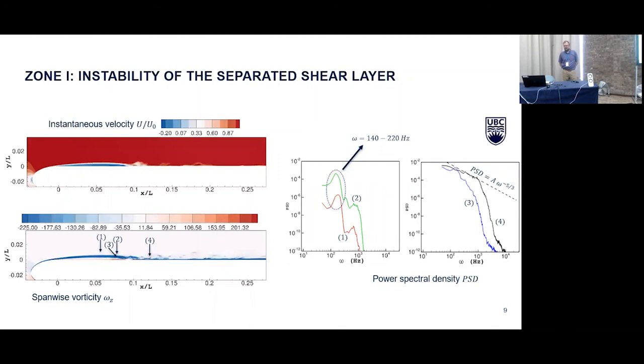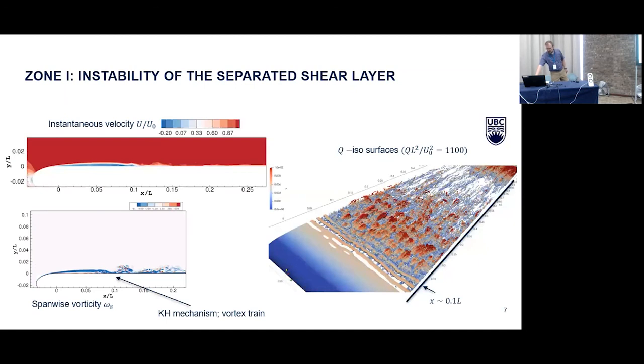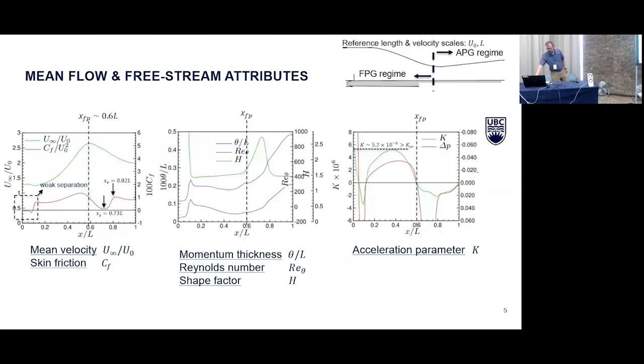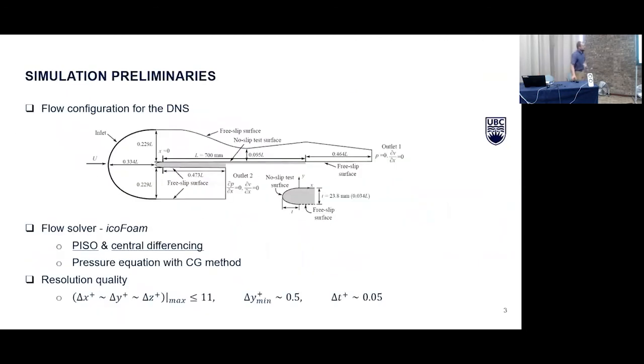One question. Can you comment on your inflow turbulence generation that you use for the simulation? We have no inflow turbulence. So we have quiescent free stream conditions. Of course, there are truncation errors and other numerical noise that result in fluctuations in the flow upstream of my leading edge. Like in this region, right here, far upstream of my leading edge, there's going to be noise there.